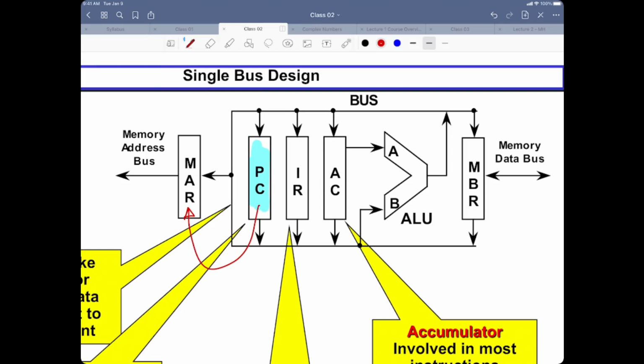That movement of PC to MAR is happening because of this. And it's a single bus, so nobody else can be writing to the bus right now. All right. I'm in MAR. Right now, my memory address register contains the address of the next instruction.